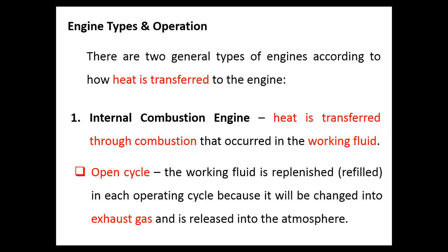And when it's combusted, we have to exhaust or release it out. So every time the cycle operates, we have to refill the working fluid all the time. So this is called the open cycle. The working fluid will change into exhaust gas after combustion, and we have to release it to the atmosphere.